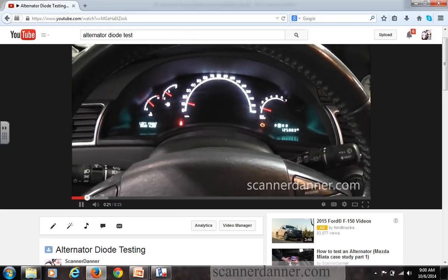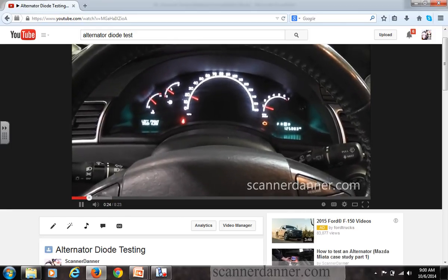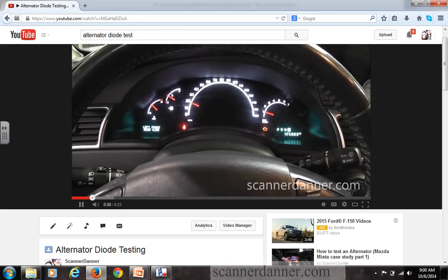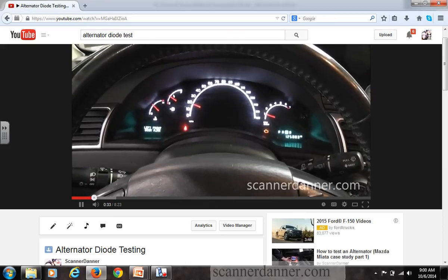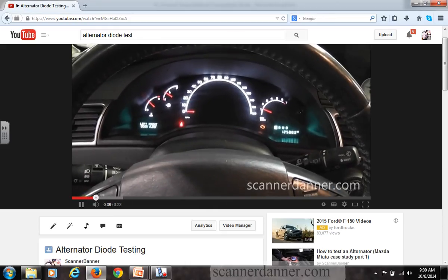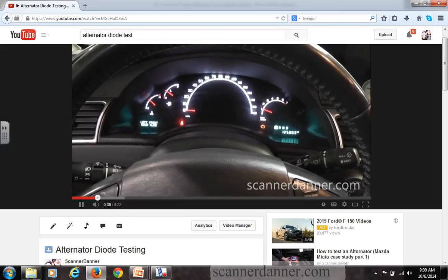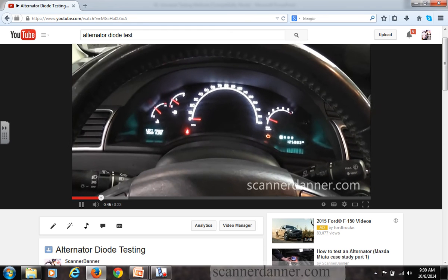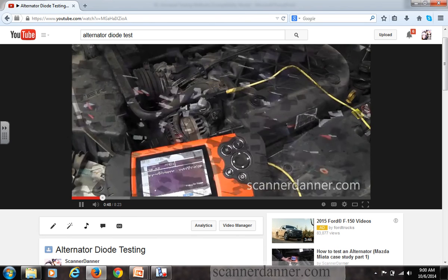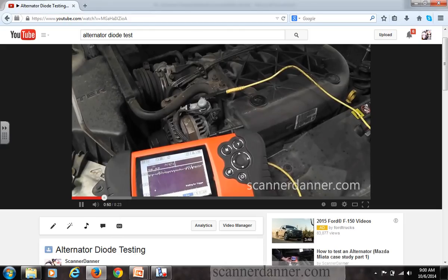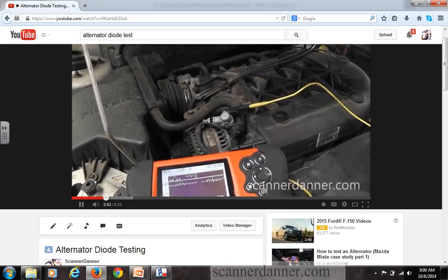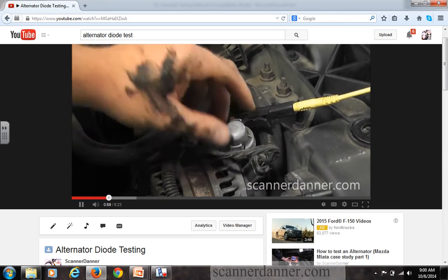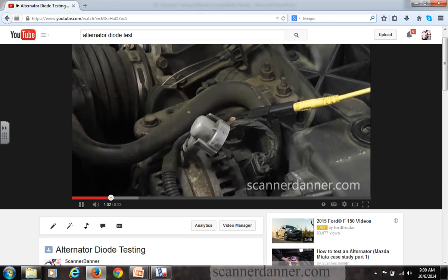right? Now, maybe a question here would be why are we only seeing this in gear? It really has to do with computer inputs, and this same signal was here all the time, but you have to understand that sometimes inputs will override a particular output. For example, the instrument cluster on this is computer controlled, and it talks to the engine computer. They talk to each other, and when that instrument cluster computer knows we're in park, it pretty much is shutting off that output of the speedometer. Does that make sense? That signal's still there in park, but why wasn't it affecting it in park? It had to do with that.